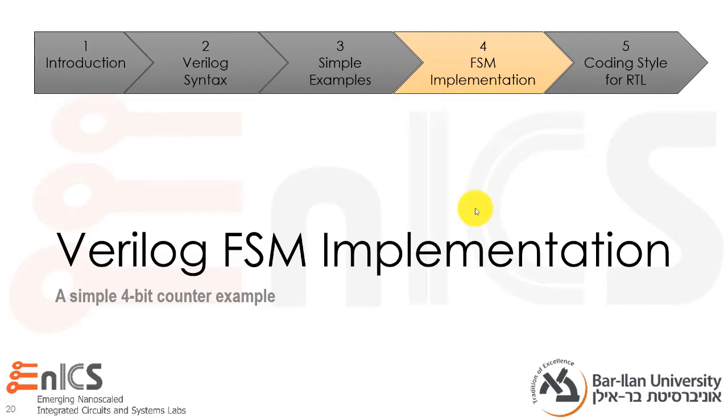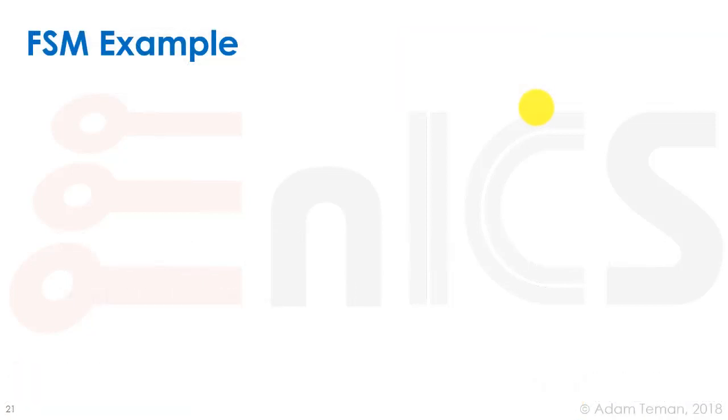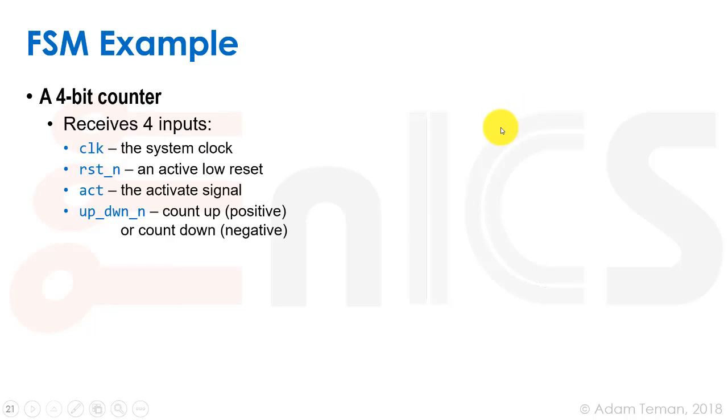So surprise, something really cool just happened. You guys know Verilog. You can actually write a state machine. You can write most of what you need to do when you're writing RTL. Let's see an example of how we can do this. We can draw a state machine, and we have a one-to-one mapping of the state machine to Verilog code. Very simple. If you can do that, well, you've just become a digital designer. So let's start a state machine example, and it'll be a 4-bit counter.